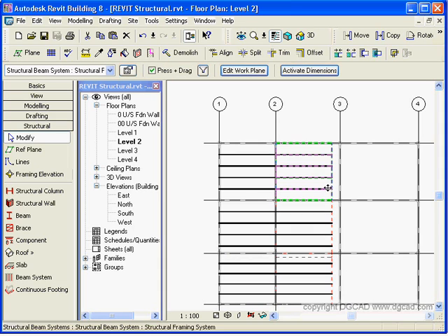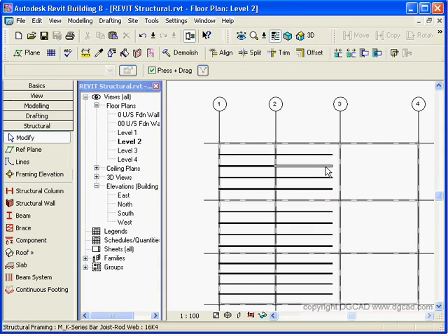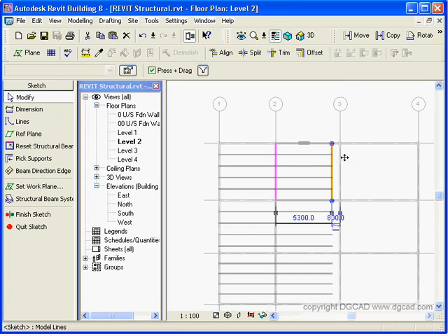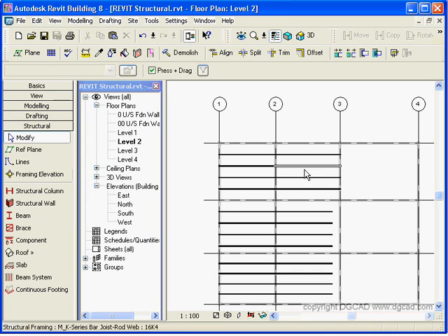So once you get a beam system in, which is actually not too bad, I can click on this beam system and go into edit. Of course, the structural guys would say, well, different span, we would not use the same system. But just to show you the diversity of it, you can go in and grab that joist system, and then you can change the depth of the joist while you're inside of there.